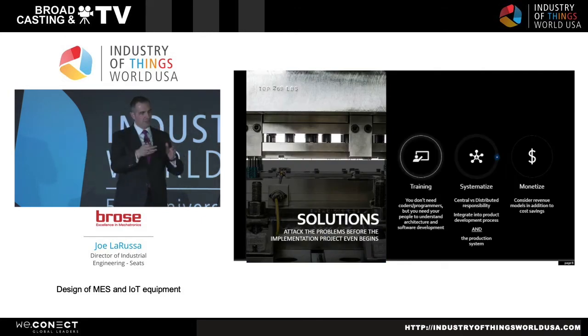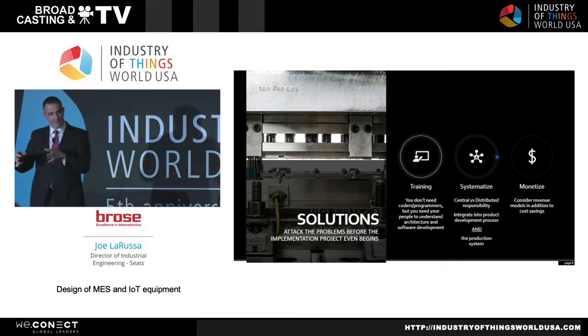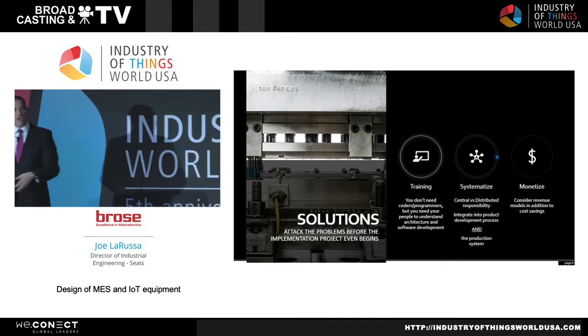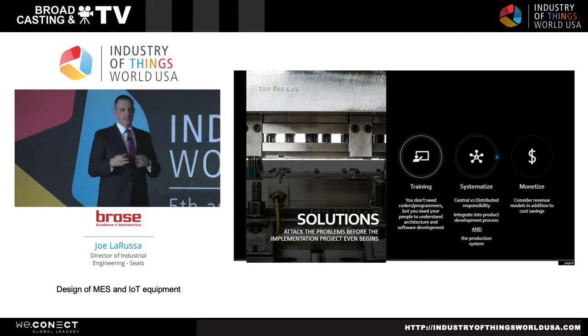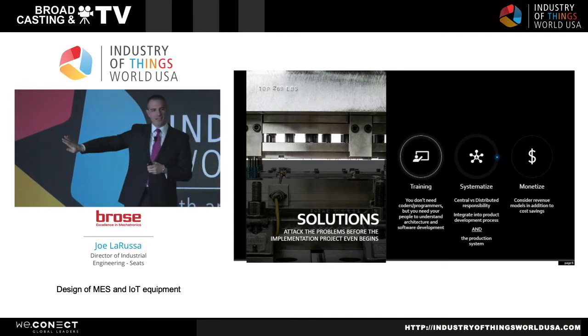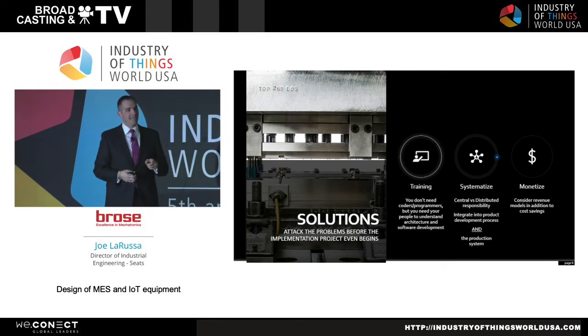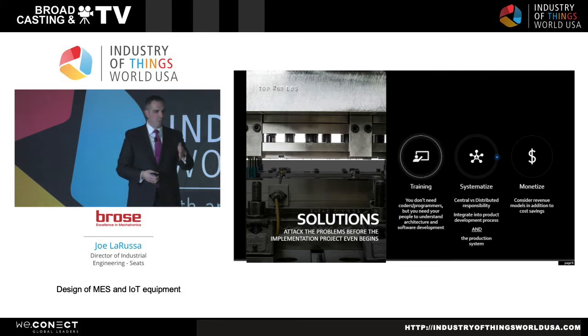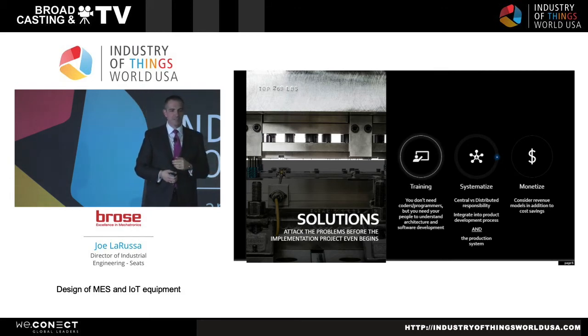So imagine the value stream: metalworking, stamping, welding, painting, assembly. Our traceability system starts in assembly. I apply a barcode and I can trace everything forward, but this is a safety critical component. It's welded. My welds can't break. So the customer says, I want higher traceability. I want to know that your welding process remains stable. I don't want to know that your assemblies are good. I want to know that your weld joints, down to that individual weld seam, are good.